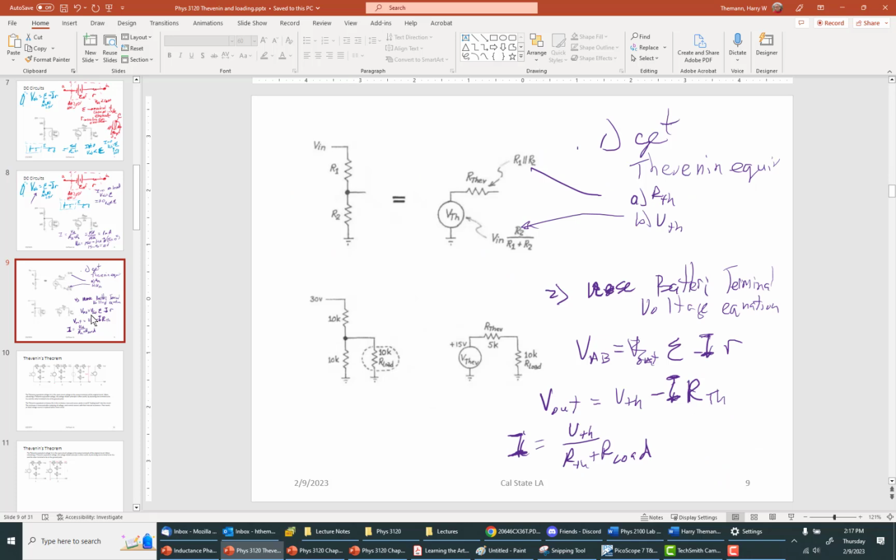So anyways, the steps for a simple voltage divider are that the V Thevenin is the no load voltage, and the R Thevenin is the two resistors in parallel. That's our basic recipe. So now I just want to go through the general definition of Thevenin, or at least not completely general, but it just shows you a little bit more. It just fleshes the concept out.